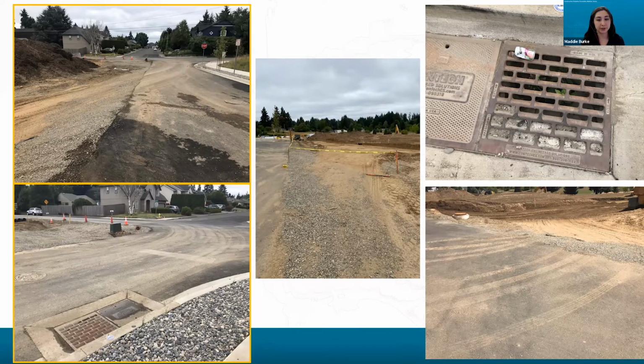So the soils and the gravel is filling up with dirt, and this is being tracked out onto the road, and it actually went down the road like a couple blocks, and that's really bad. A street sweeper is not the fix-all for erosion and sediment control, and neither is silt fence, which I'll get into later. But yeah, you don't want to just say, oh, I'll call a street sweeper, no big deal. You want to prevent that sediment from getting onto the road in the first place.